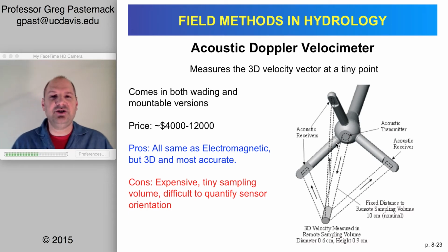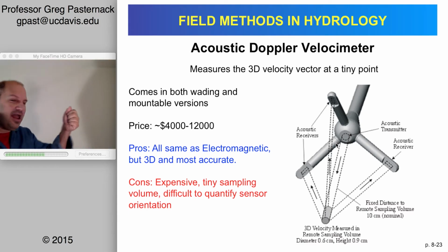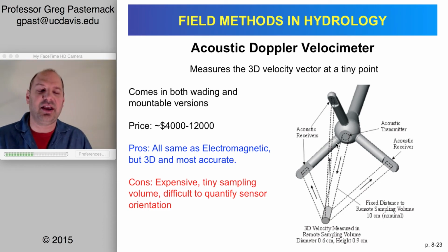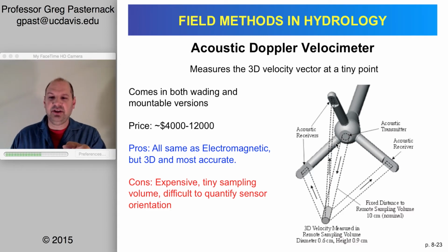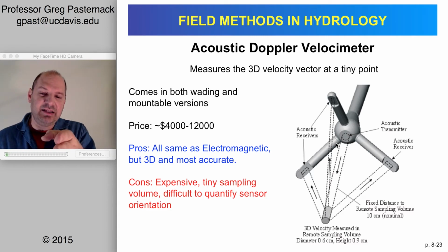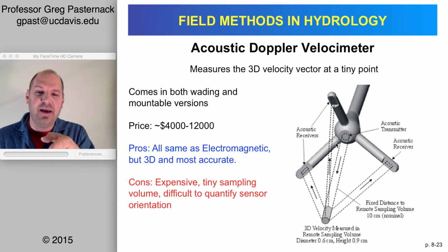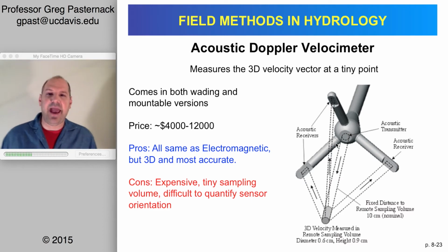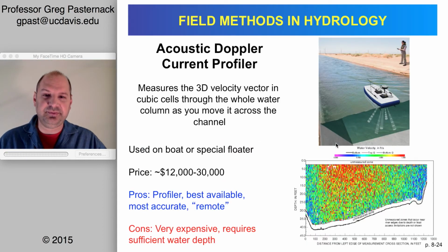It's a challenge. You can't look over at the bank and say, okay, now I'm perpendicular to the bank. Banks are very complex. Unless you're in a canal, it's virtually impossible to do that. You can orient the sensor so that, watching the digital readout, the lateral and vertical components are basically zero, so I know I'm right in the current. So I can orient it relative to the streamlines of the flow, but that's not necessarily perpendicular to the banks. And so that's a challenge.